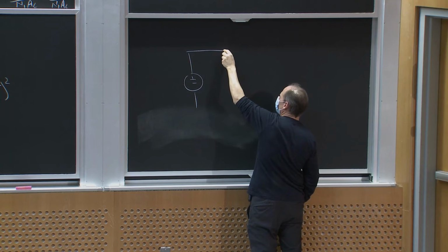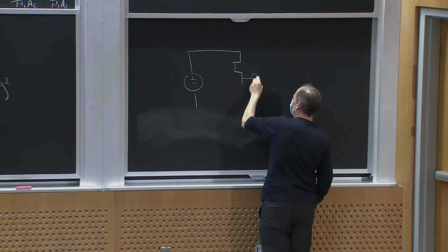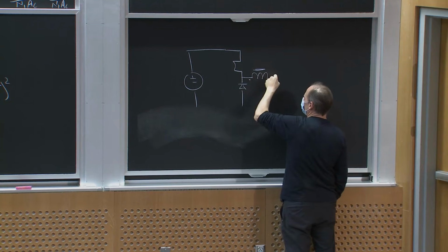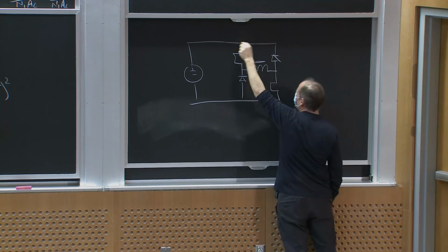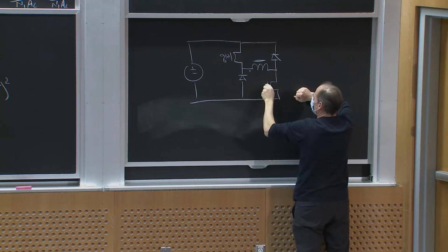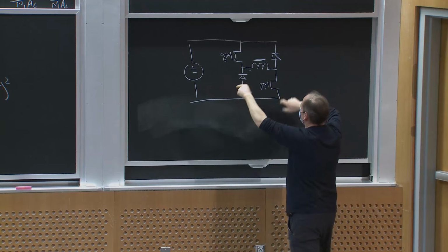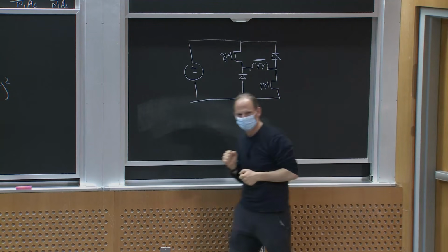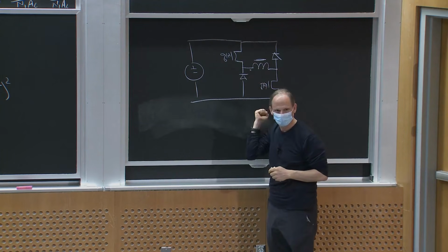In the first part of the cycle, I apply a positive voltage through a pair of switches. And in the second part of the cycle, I'll turn on this, this is Q of T, and this is Q of T. So I apply a positive V in across the transformer, just the way I did up there. In the second part of the cycle, the switches turn off and the diodes turn on, and I return the magnetizing inductance energy to the input. This can work up to a duty ratio of 50%.